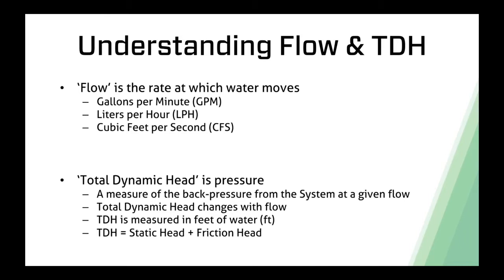So where that phrase comes from is because it's the total dynamic head, because it's the sum of three separate components. We're going to talk mainly about two, but total dynamic head is the sum of static head plus friction head, plus in certain circumstances, more advanced applications, you may have something called operating head. And we're not going to get too deep on that, but I might mention it a time or two in the presentation.